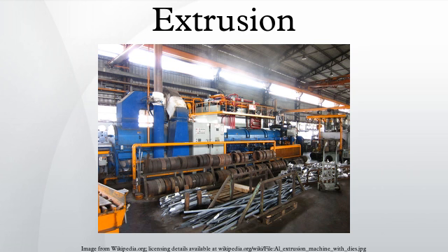Hollow cavities within extruded material cannot be produced using a simple flat extrusion die, because there would be no way to support the center barrier of the die. Instead, the die assumes the shape of a block with depth, beginning first with a shape profile that supports the center section. The die shape then internally changes along its length into the final shape, with the suspended centerpieces supported from the back of the die.